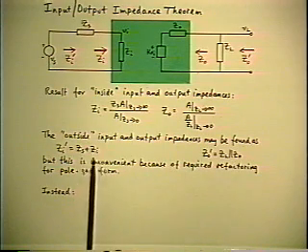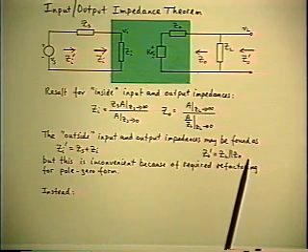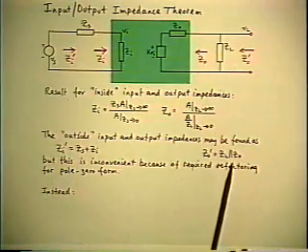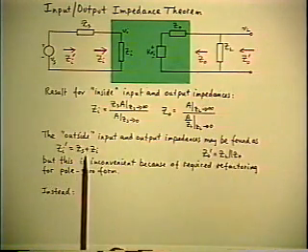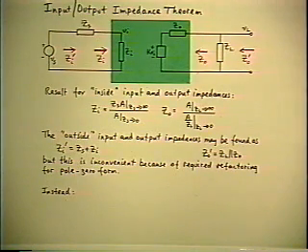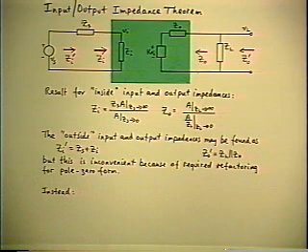So if you start knowing what the Zi and the Zo are, and the Zs and the Zl, in factored pole zero form, and you want to find what the outside impedances are, then you have to perform a summation of factored pole zero functions, which means cross-multiplying numerators and denominators, collecting powers of S into a new polynomial, and refactoring a new polynomial. And that's messy. So even though the formulas are very simple, the application is not so simple.